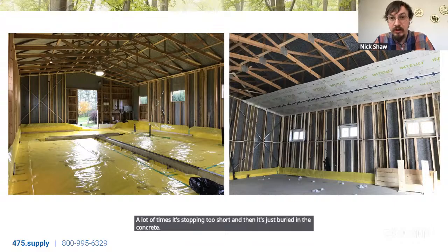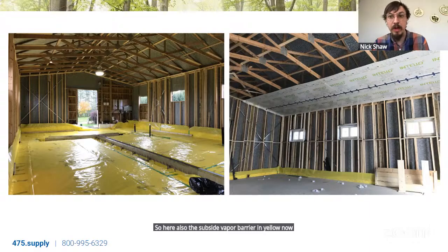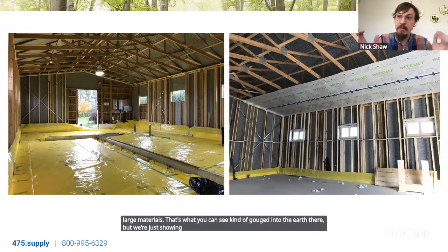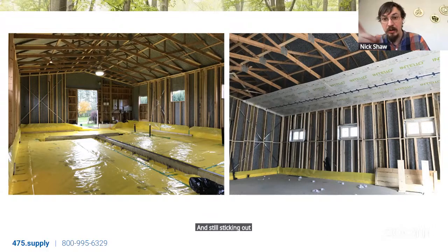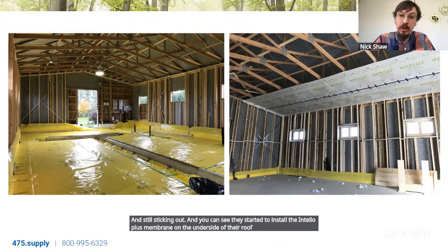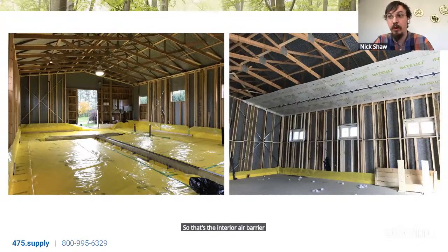So here also the subslab vapor barrier in yellow now. I believe this was a brewery project where they had this track system for maneuvering large materials. That's what you can see gouged into the earth there. But we're just showing that it's running long at that perimeter. On the right, you can see that the concrete was poured and still sticking out. And you can see they started to install the Intello Plus membrane on the underside of their roof system on that image on the right. So that's the interior air barrier and primary air barrier for the walls.